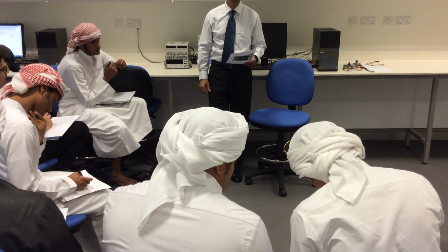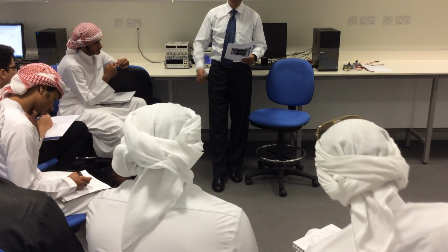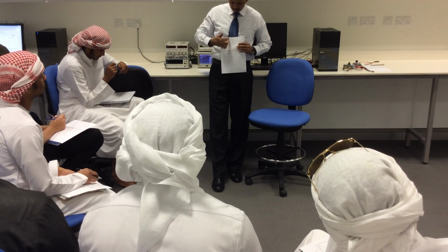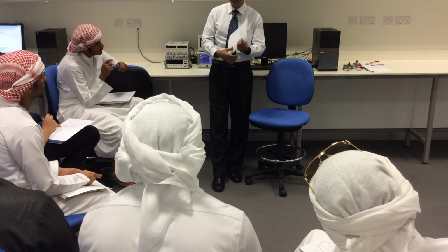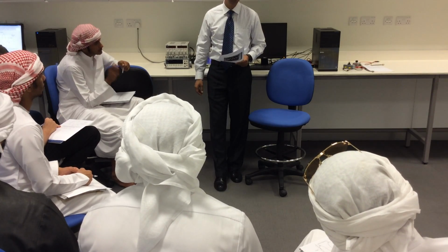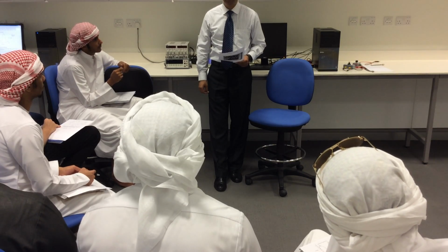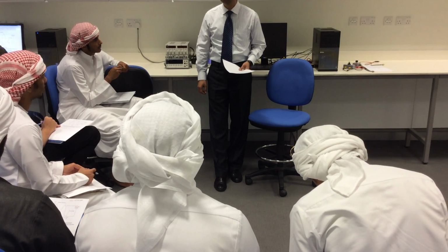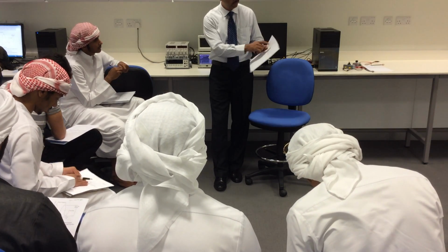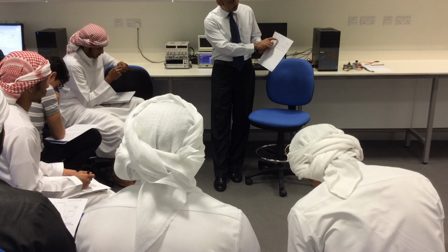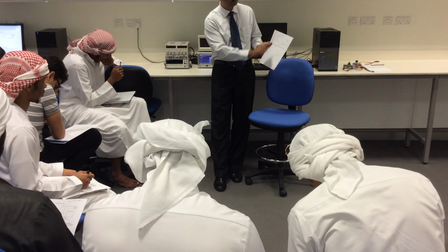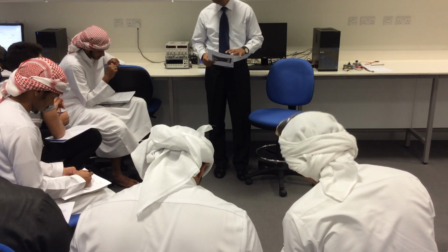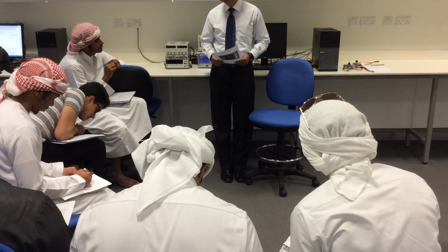Now there is another thing, which is peak voltage, which is the voltage going just on one side. The easy way to find the peak voltage is peak to peak voltage divided by 2. So peak voltage is 3, and you can see it from here. It starts from 4, so it's 5, 6, 7, 3 volts. So peak to peak voltage is 6 volts in this case, and peak voltage is 3 volts.